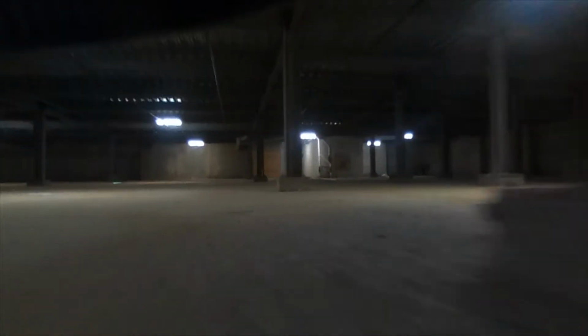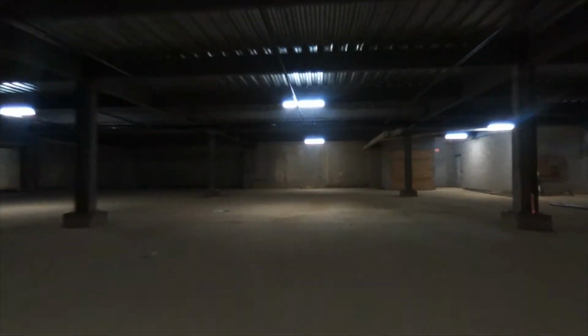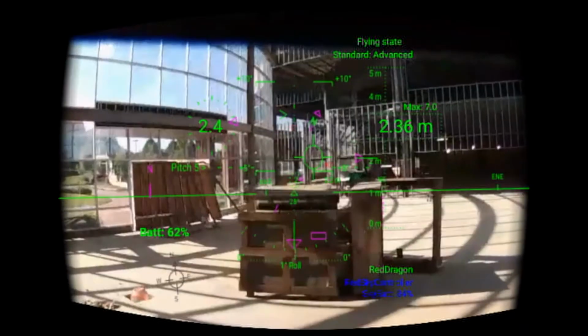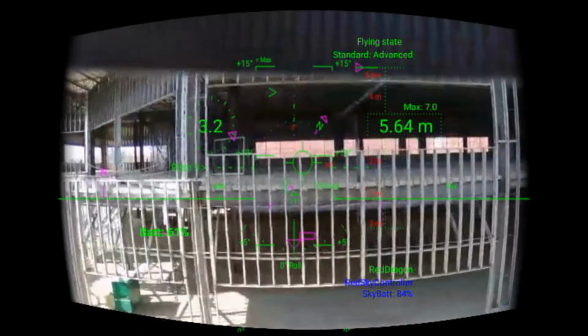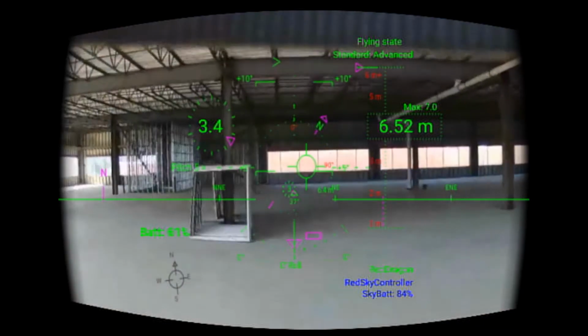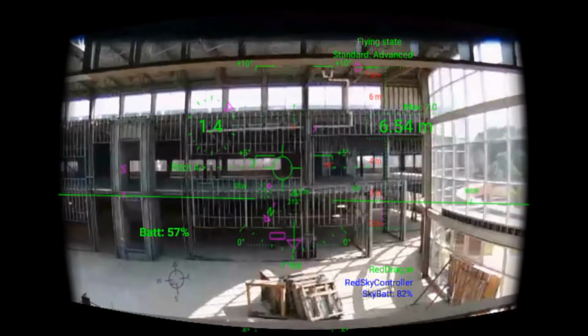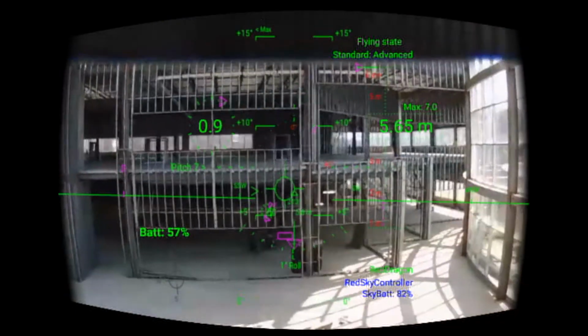When I first implemented the FPV, we were still crashing fairly often. It was marginally easier to fly, but we were still crashing, especially on higher speed turns. Then one day I decided to trust the birdie. You see, in earlier tests we found we used the flight path vector as a guide, but mainly relied on visual cues from the video feed to estimate the required stick input. When I kept my eye on the birdie, I noticed I could then easily guide it to where I wanted it.